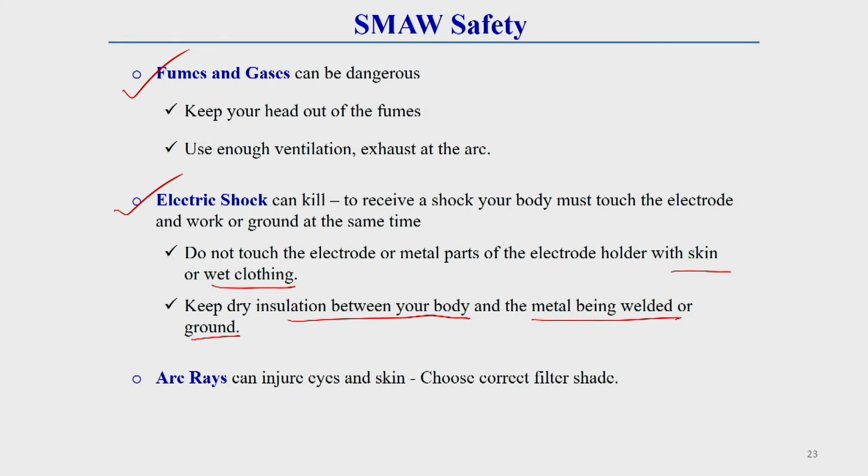Generally for doing the welding operation, some gloves are used, and there are separate types of gloves and other things used for this welding operation. So always keep this in mind. You should not touch the workpiece and electrode simultaneously, and you should keep dry insulation between your body and metal being welded or ground.